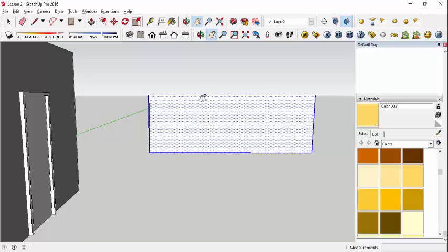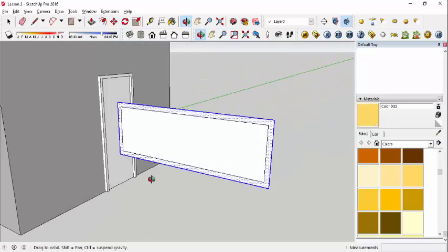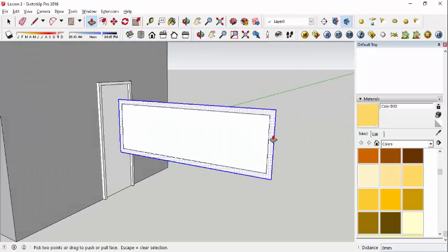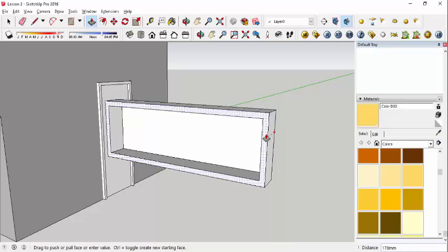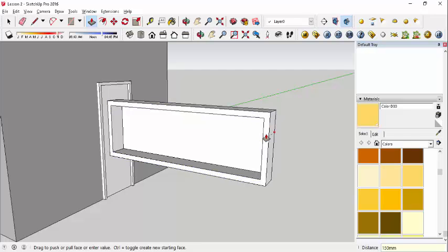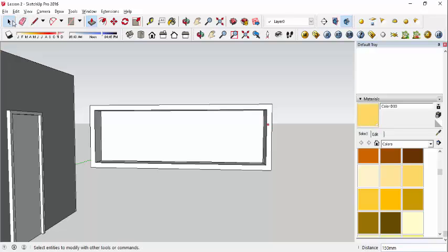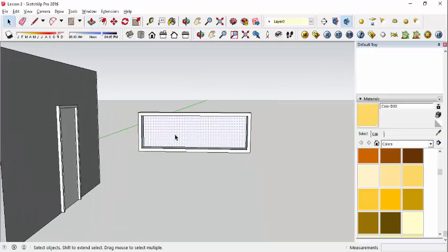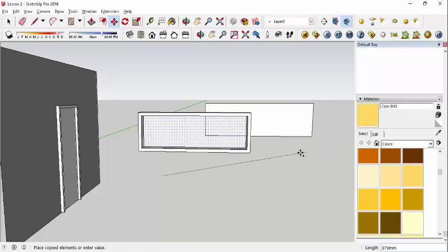So let's click on offset, which is F, or you can also use this. Okay, so F on your keyboard. While that command is still on, click on 40 on your keypad or numeric pad or keyboard. Okay, hit enter. Now that's the frame. I'll use push. The thickness of the wall is 200, right? So let's use, let's say, 150. Okay. Now that I have the outside framing, I click on this one and copy it outside again to do another framing. So that's M and then Control and then drag it outside.